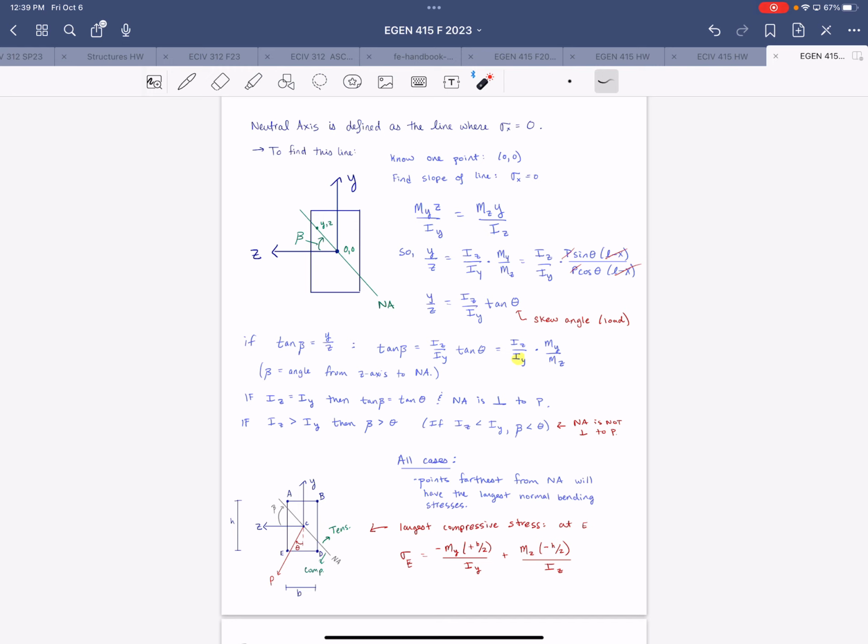So you were doing this in steel, and then you were sizing the beam based on that? You probably did calculate the moments about each axis, and then you went through that process using the steel manual to select a size based on that, with the respective axes considered. So we're doing the same analysis, except just finding the internal stresses.